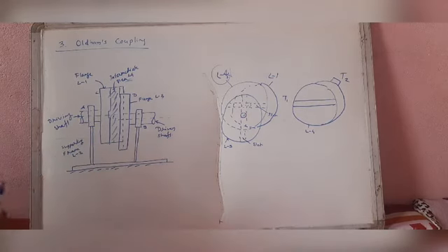If the distance between the axes of the shafts is constant, the center of the intermediate piece will describe a circle of diameter equal to the distance between the axes of the two shafts. Therefore, the maximum sliding speed of each tongue along its slot is equal to the peripheral velocity of the center of the disc along its circular path.